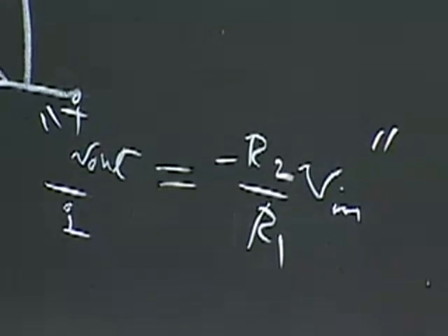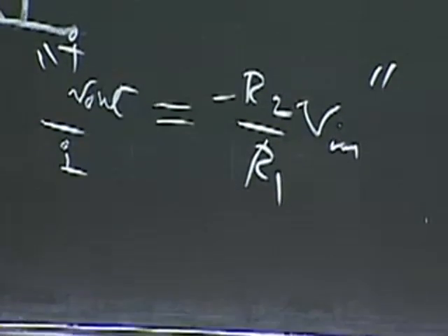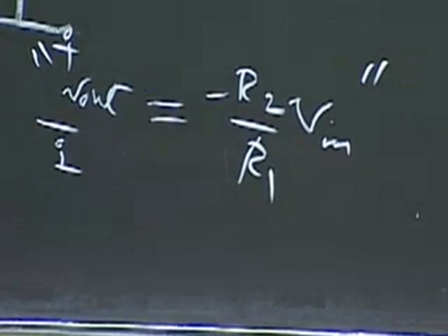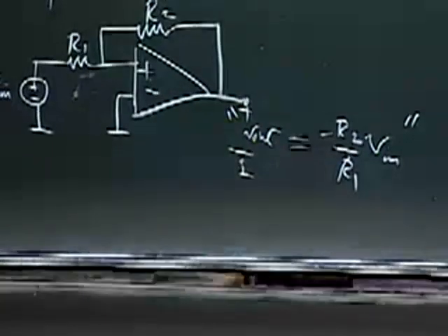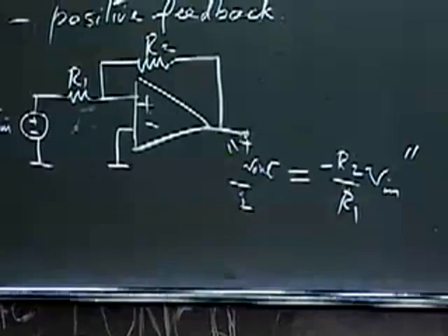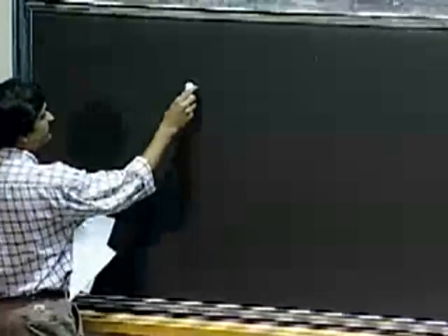Okay, and let's go ahead with the analysis and see what is basically different about these two. Okay, and first of all, I'll confirm for you that our naive analysis we've seen so far will give rise to that expression. So let's go ahead and analyze that circuit. And to analyze that circuit, what I'll do is replace the op-amp with its equivalent circuit. So if you remember,